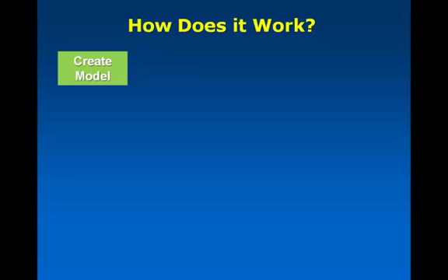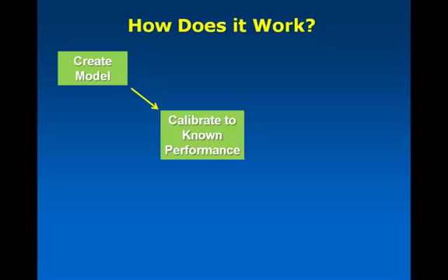So for the most part, the way that we see our clients using this software, and the way that we indeed use it ourselves when we are doing projects for our own clients, is that we start by creating a model of a wastewater treatment plant in GPSX and entering in all of that information about the tank sizes and the clarifier depths and so on. And then we go through a process of calibration of that model.